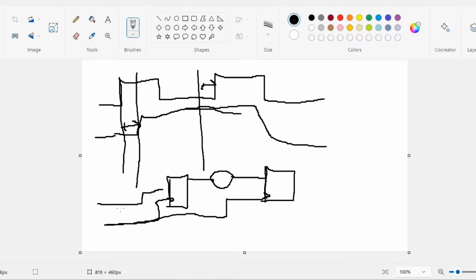How do you get it? There is one thing forming between these two wires. You can see a capacitor, right? Yes, correct. We say it as coupling capacitance. So due to this coupling capacitance, there may be a difference in the launching and capturing edge of the clocks. So there may be a delay.